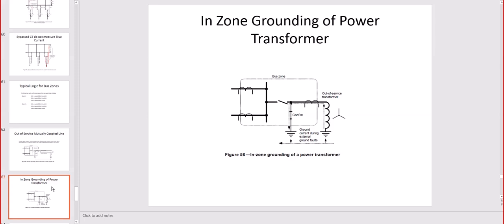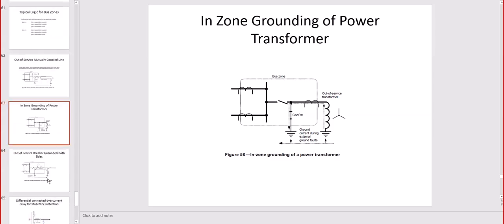In-zone grounding of power transformers, usually solidly grounded for low voltage, up to 1 kilovolt, and high voltage, above 70 kilovolts. In between, from 1 kilovolt to 70, is medium voltage, which is resistive grounding and can be high resistive with maximum 10 amps neutral to ground on short, or low resistive with up to 1000 amps neutral to ground.